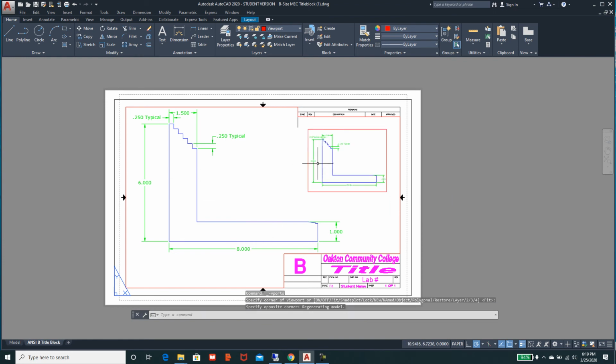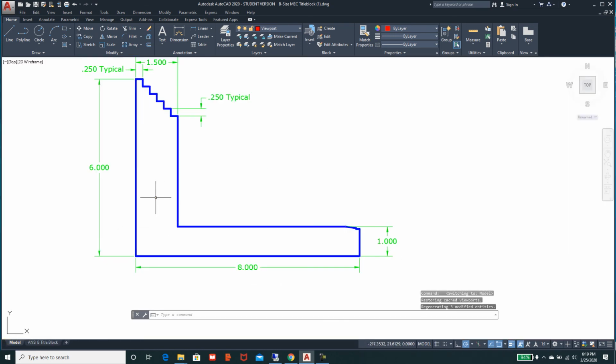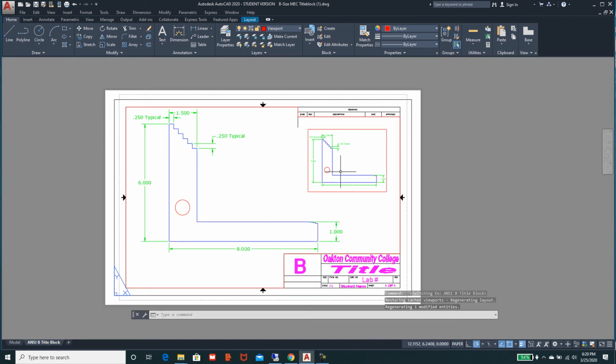And then you can see what it does is it puts the object, and it's kind of like a camera, into model space here, where whatever I do here in model space, if I decide I want to put a circle right there, I come back here, it's reflected, and it shows a view or a viewport to that. And if I do something in any of these viewports, I'm working on the same object. It's just multiple instances.